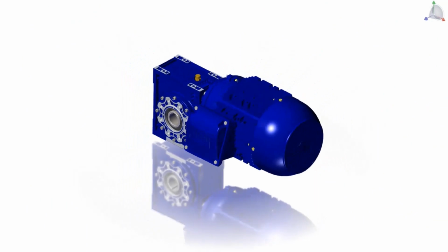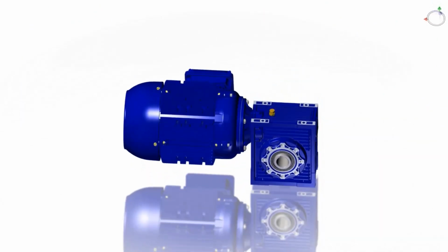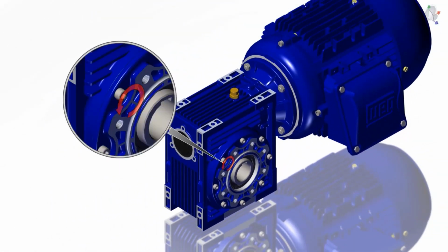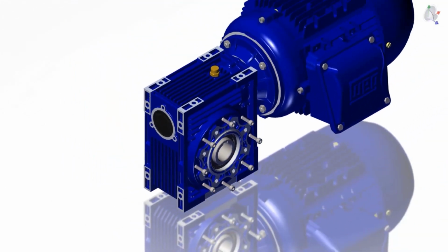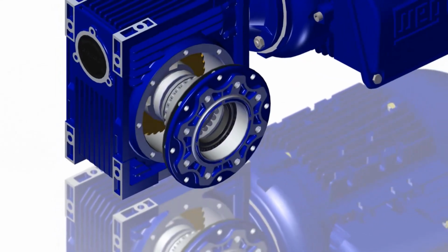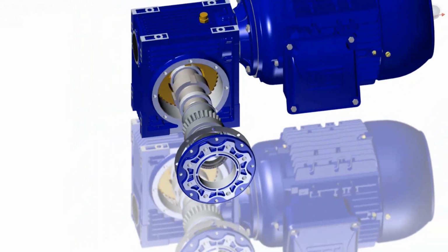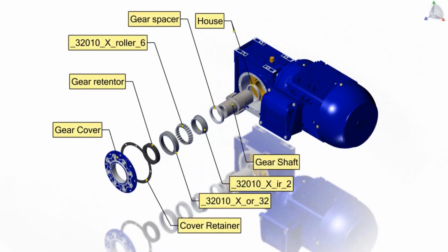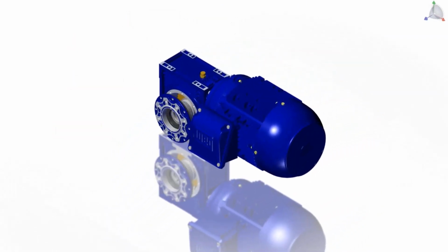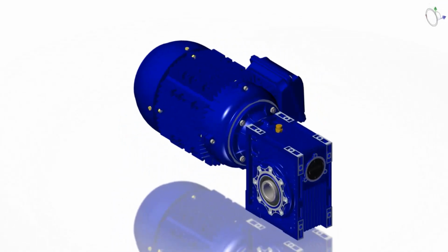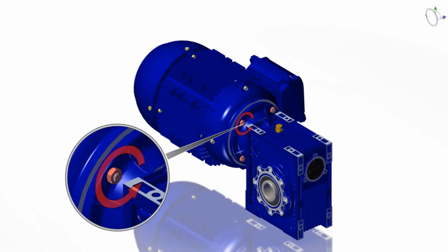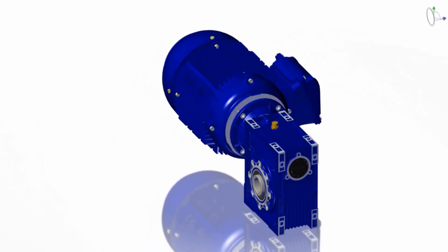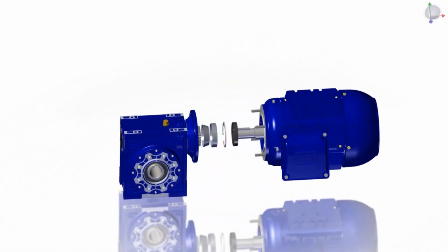So in the Composer, animation has a short learning curve because animations are so easy to create when utilizing the existing project views. You can simply drag and drop the views, and you can generate this kind of animation as well. The automation built into the timelines allows you to create as changes are made or views are added. You can add the exploded views. You can add your callouts, as you can see on my screen. You can also define the events as well, and also add the motions for this. For example, I have added motion for the screw removing and other things.